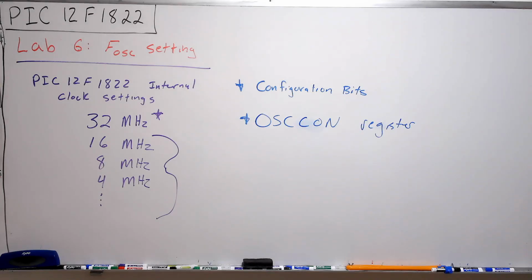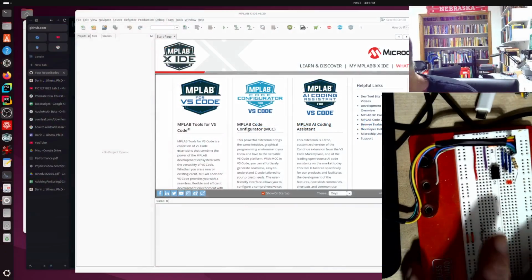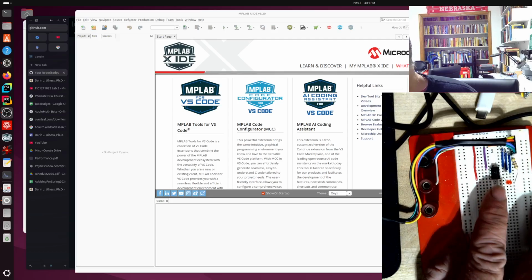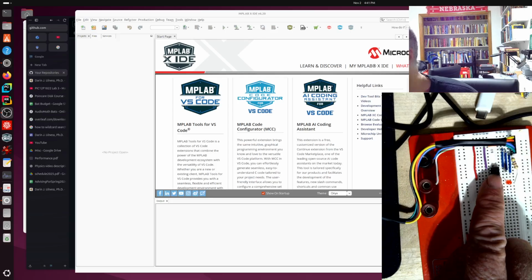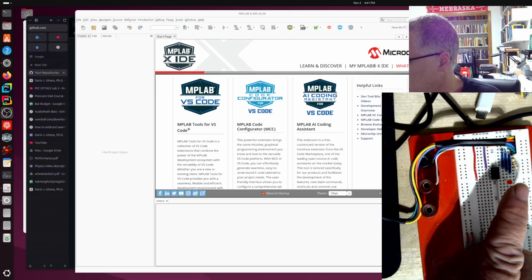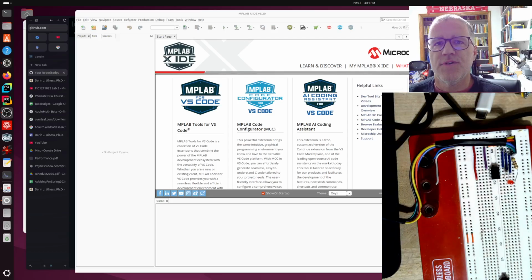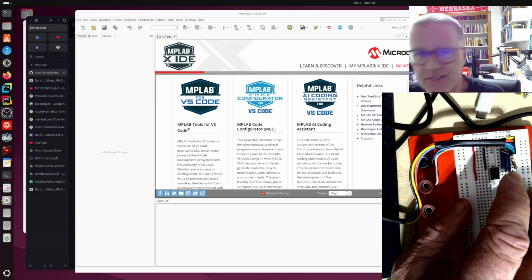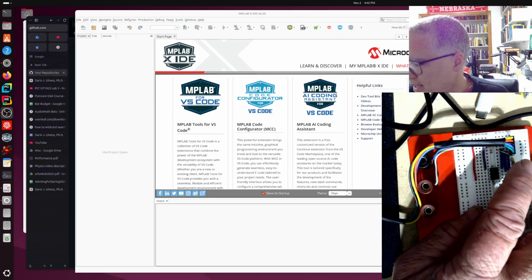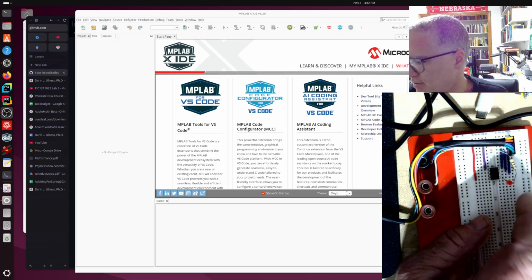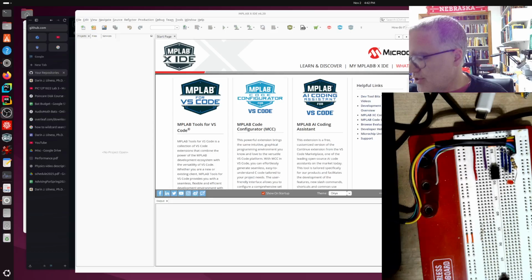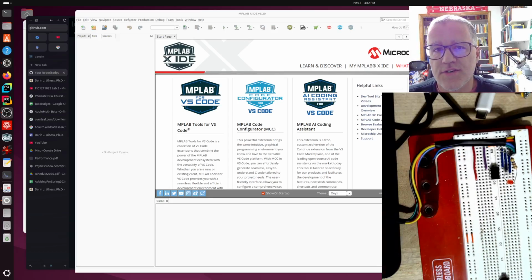go to the computer. And so the setup here is very simple. Just have the PIC right here, and then just an LED to show. We'll just blink an LED, and it'll just change with the clock speed of the PIC. So we won't change the code, we'll just change the clock speed, and we'll get a sense of that change here. And then this resistor is just going to ground so that we're not running the LED all the way to ground. So this is just blinking, like the earlier lab, but now we're going to change the